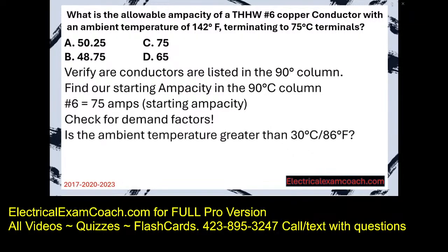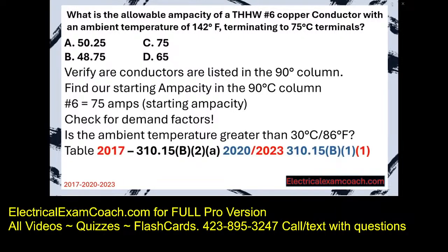Is the ambient temperature greater than 86 degrees Fahrenheit? It is, so there will be a demand factor. We're going to head to our respective table depending on our code cycle, and we're going to go find our correction factor.